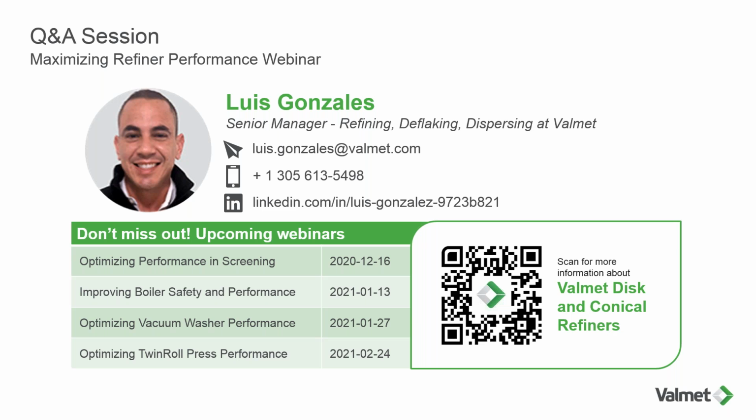But to the second point, what makes the wear faster than normal? So the tram that I mentioned earlier, if the shaft is not properly perpendicular to that refining surface that I mentioned, that door datum, that's the critical spot that we need to make sure that all plates are parallel to that. If you can imagine, as I mentioned earlier, the pressure on both sides of that rotor is going to perfectly balance itself between the two stator positions.